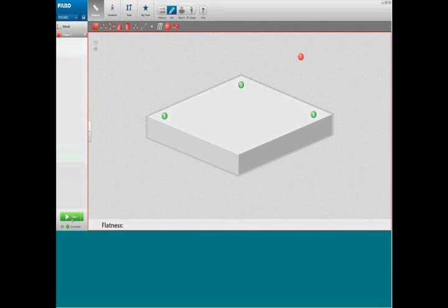To the bottom of this panel, we have the Start menu. This allows us to remeasure the inspection plan from the beginning for batch inspection. At the foot, we have the Quick Preferences. If we open this, this is where the user can choose the coordinate system type. So we can choose Cartesian, spherical, or cylindrical. We can also select the unit format here, either millimeters or inches.